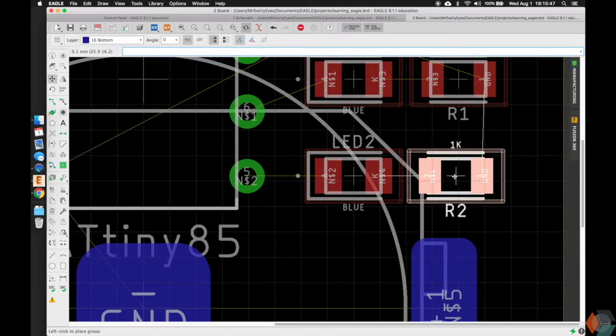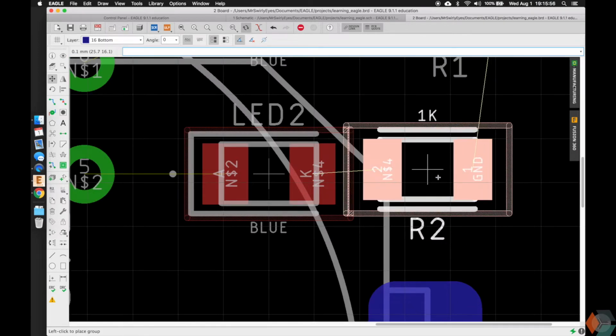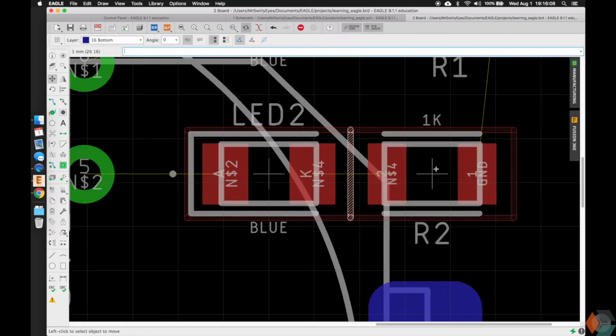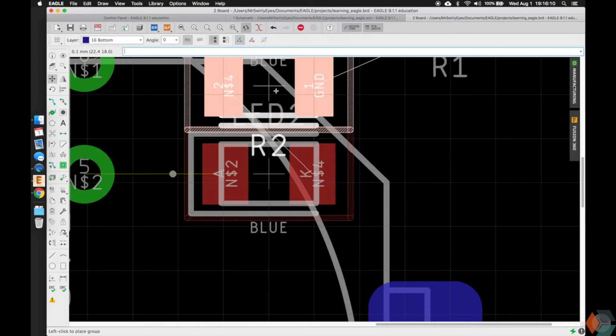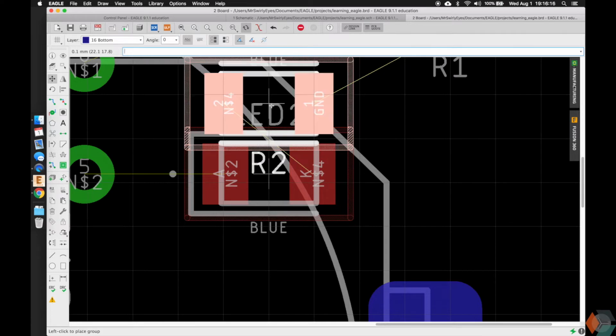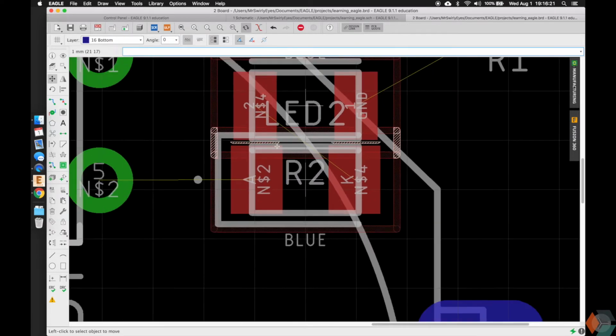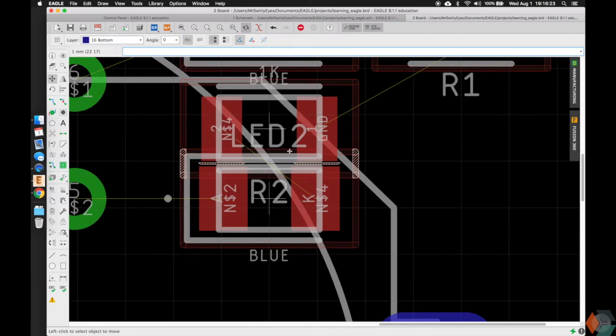And you're going to notice these red outlines here. These red outlines are for you to design without getting things too close together. It'll be flagged by the DRC if they're inside each other. And the reason is because when you print your board, if you put something too close like this, see how the DRC is not yelling at us about the pads? Put it a little bit closer. Now the DRC is saying this is way too close. Our manufacturing machines may not guarantee your design to be working in that way.